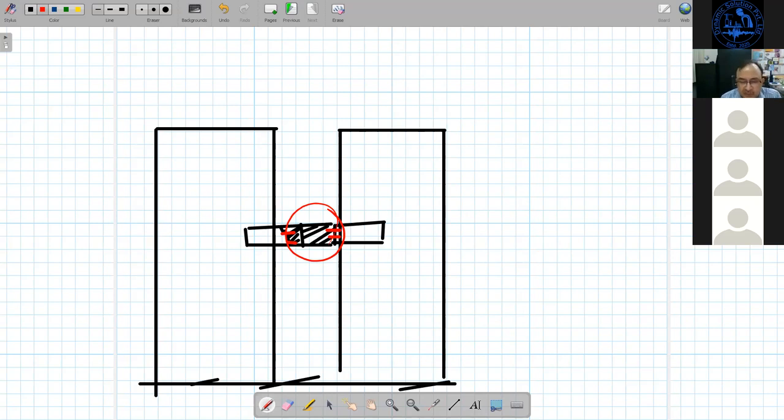The reinforcement of the slab should be anchored into the shear wall of the lift well.